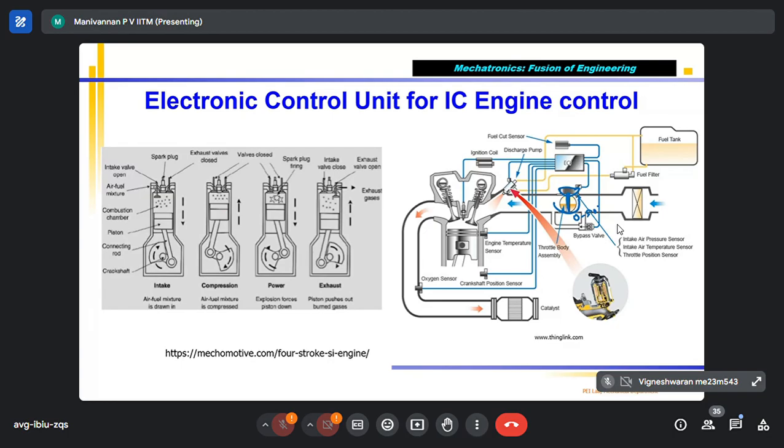Now the dots show the fuel-air mixture, fuel plus air. It is getting compressed. During compression, the piston is going up from 100 cc, and it is going to get reduced to 10 cc. Compression 10 to 1, for example, correct?